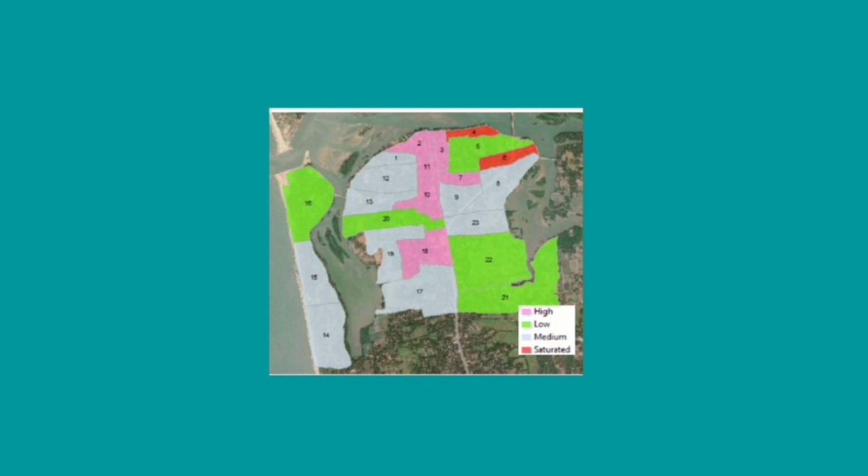So once you get this data, after laying the pipelines, it will become very easy for you to distribute this population, right? Because now you don't have to distribute an equal amount of water demand on each node. Rather, the nodes falling in the respective ward boundaries will be decided by its existing conditions.